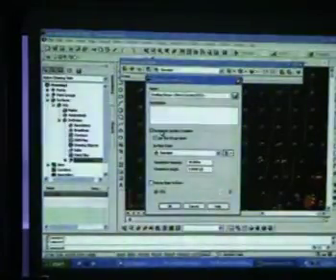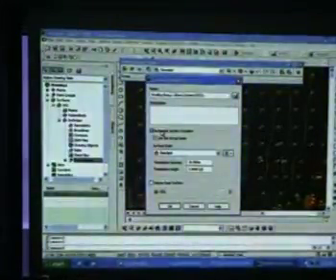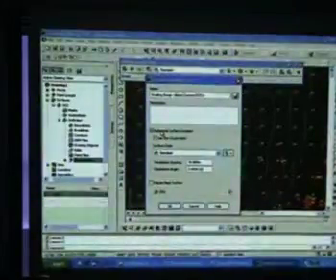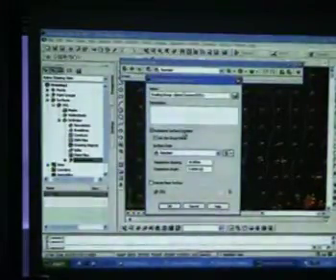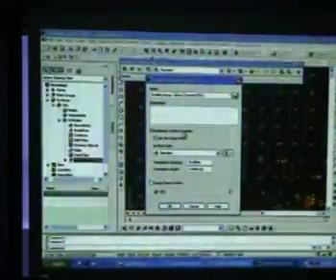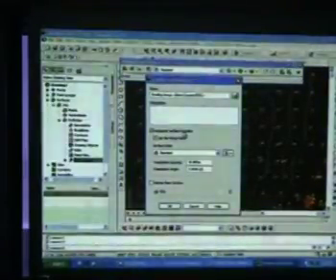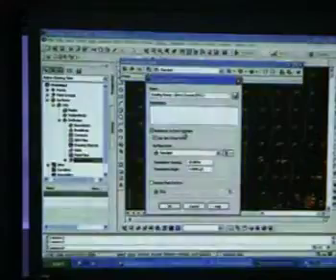If you like, you can create a surface automatically on this. Meaning, instead of creating our own surface called proposed level, you say I want to use this grade inside this. You just click automatic surface creation. It will create a proposed level for you automatically from this grade. But the name of the surface, of course, will be called grading group 1. So that's why we say use the group.